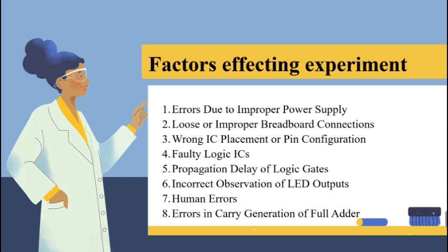Errors may occur because the LED's polarity is reversed, the current limiting resistance is absent, the LED is faulty, or the user misreads dim illumination. To prevent this, verify LED polarity, use suitable resistors, replace dim or damaged LEDs, and confirm output with a multimeter if necessary.